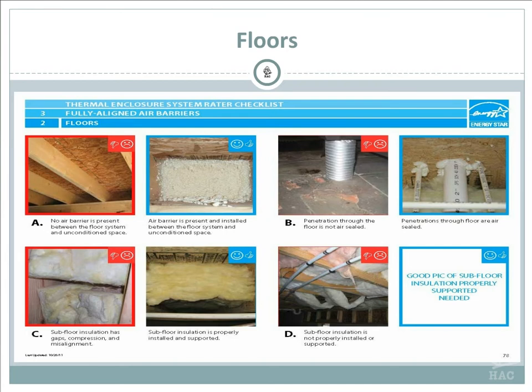Again, the next one on the right, we talked about all the penetrations going through the attic or through the crawl space or the floor, whatever it may be. In this particular case, we're talking floors. So this is plumbing insulation or plumbing pipes that are going up through the floor. All of them have been sealed. Again, no air penetrations coming in.